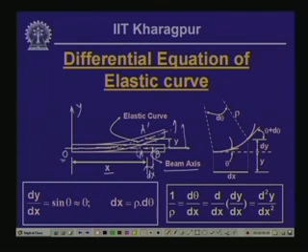and if we exaggerate this figure and plot it over here, it looks like this: this is dx, this is A and this is B. After deformation, this is A dash and this is B dash. Now, point A has undergone a deformation which is y, indicated over here. Consequently, over a small distance dx, the point B has undergone a deformation which is y plus dy. So, this stretch is dy.